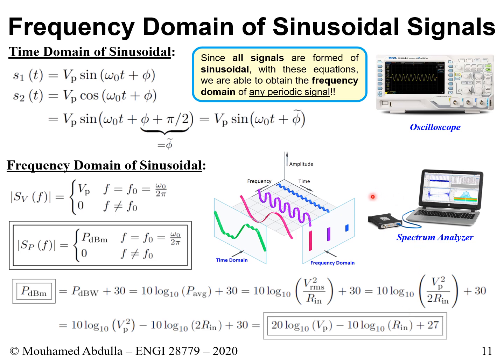And also, because you're using a device, it has an internal resistance, and the internal resistance is here. Now, I've seen some people do a back of the envelope estimate of what the power should be, and they assume that the internal resistance is 0. But the internal resistance will have a contribution. If, for instance, you enter an internal resistance of 50 ohms, let's do 10 times log of 50. This is a contribution of 17 dB, so you need to subtract 17 dB.